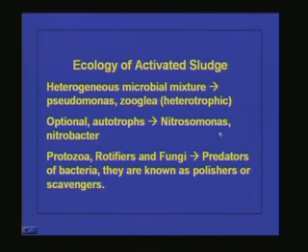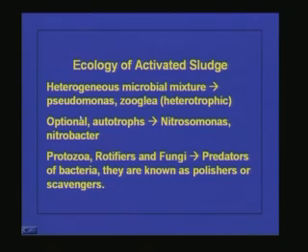These microorganisms come into the picture whenever we talk about ammonia oxidation, because we know that protein contains a lot of amino acids, and so naturally the wastewater will contain a lot of organic nitrogen. If you aerate the wastewater for a long time, what will happen? First, all the organic matter will get oxidized, and afterwards the organic nitrogen present in the wastewater will be converted to ammonia, and that ammonia will be further oxidized to nitrite and nitrate. So, Nitrosomonas and Nitrobacter are responsible for the oxidation of ammonia to nitrite and nitrate.